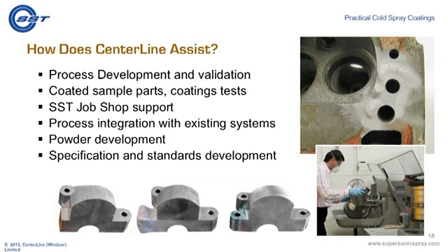Here's an example of a customer who had actually misdesigned a cam cover. Originally, it only had 2 points upon which to fasten to the block. The connection was not intimate enough to prevent any oil leakage. For him to redesign, remanufacture these cam covers would have taken months to accomplish. He approached us and asked us if we could actually cold spray material to allow him to machine a third point of contact, a third boss. We did this very quickly. The customer used his own machining capabilities, tested the 3-point cam cover where it passed immediately. Again, these are some of the coating and mechanical experience that we can share with our customers.